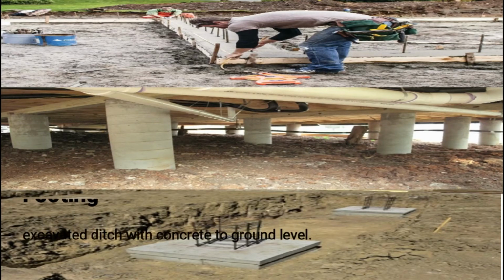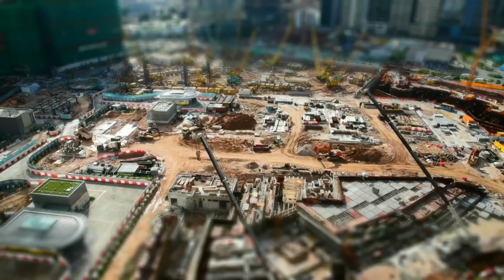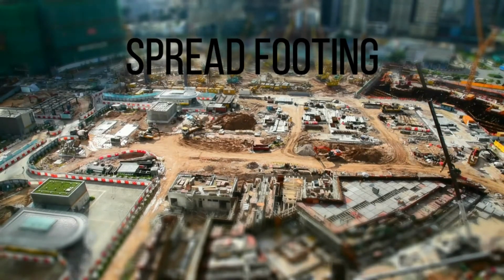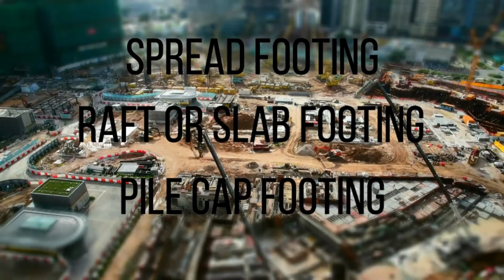3. The footing is the part of the foundation that supports the concrete slab, floor joists, or blocks. Footings are formed by filling an excavated ditch with concrete to ground level. The footing runs along the entire perimeter of the structure. Three kinds of footings that are often used. 1. Spread footing. 2. Raft or slab footing. 3. Pile cap footing.